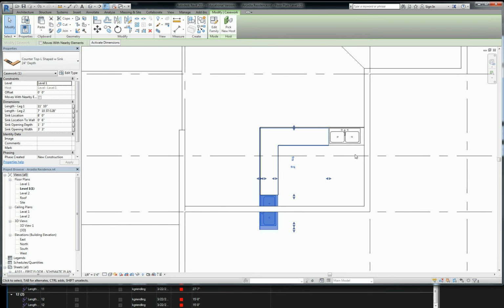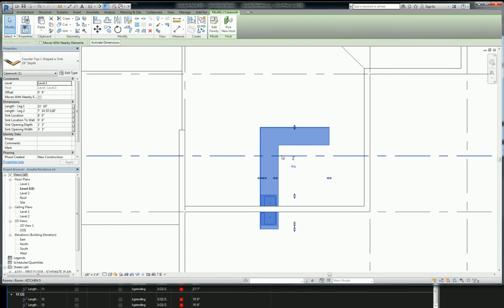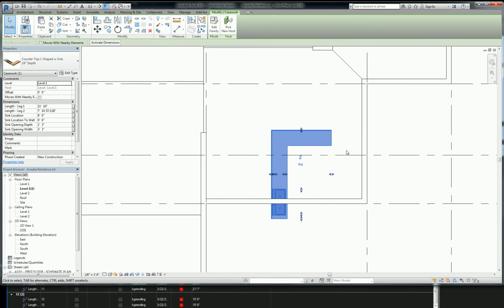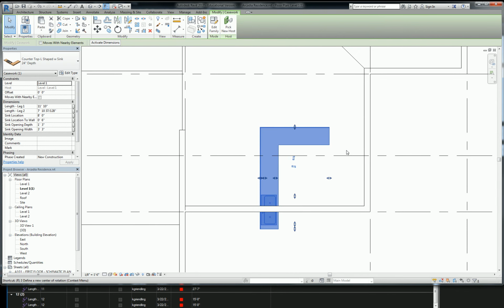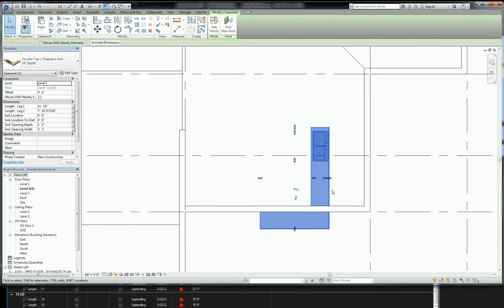I mirrored it, and I forgot to uncheck copy. So, DM, click on the checkbox for copy, and it will uncopy. Then I'm going to do that again. Even though it's still in the wrong position, now I just need to rotate this thing 180 degrees. Boom. And then you can just drag it and drop it. It'll snap to the wall, which is kind of nice.